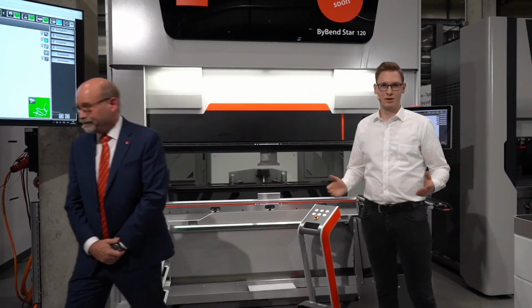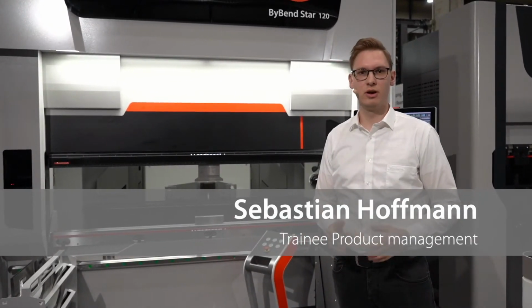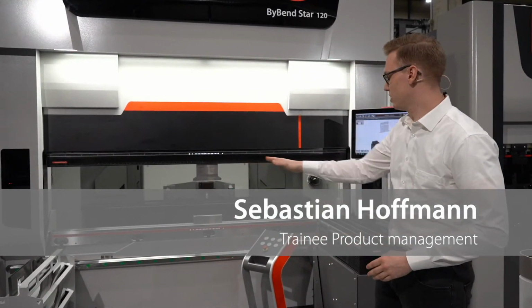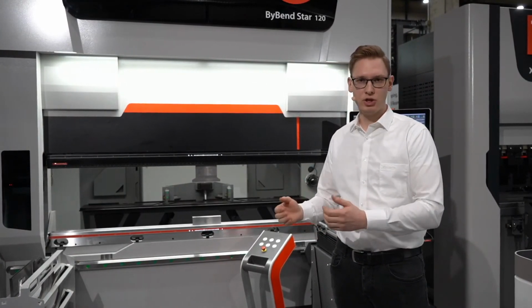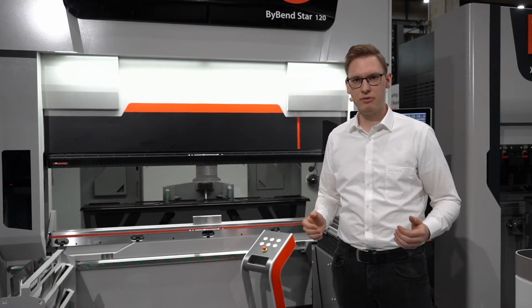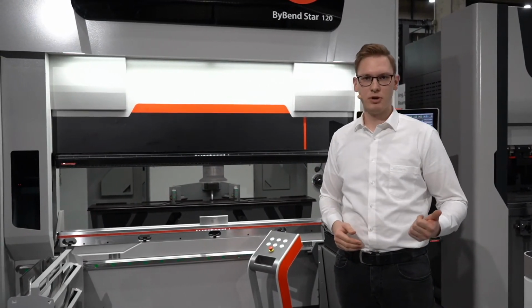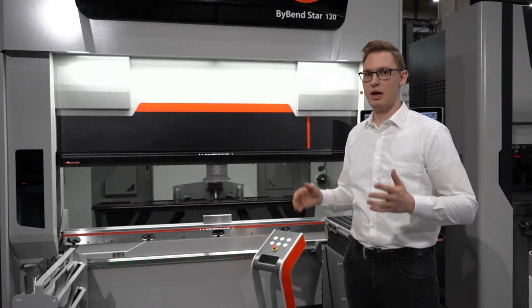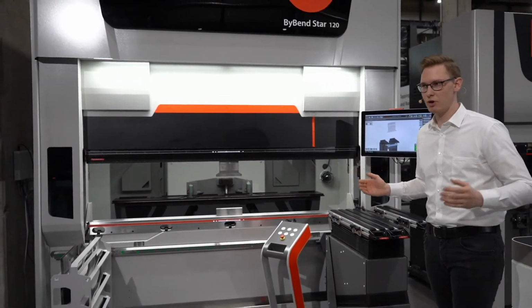Sebastian is going to explain why you have to wait a little bit and why you want to buy it. Have fun. What you can get is a machine with 120 tons of pressing force and 2 meters bending length. So you will be able to bend jobs with up to 6 millimeters material thickness over the complete bending length. So you're really flexible, really fast, and really precise as well with this machine. And this machine is a really speed monster.